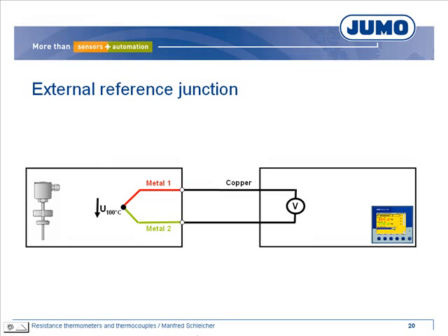Generally, thermocouples and field devices can be connected using a copper wire. In that case, the reference junction is on the terminals of the thermocouple. The device measures the voltage of the thermocouple minus the voltages of the terminals and calculates the temperature differential. To identify the process temperature, the temperature differential and the temperature of the terminals have to be added up.